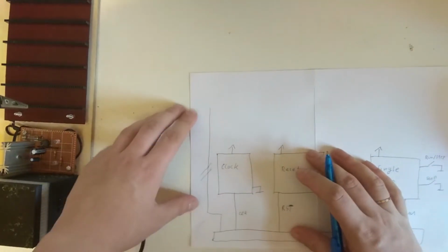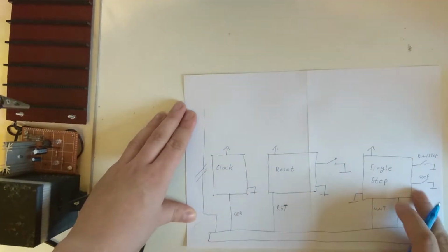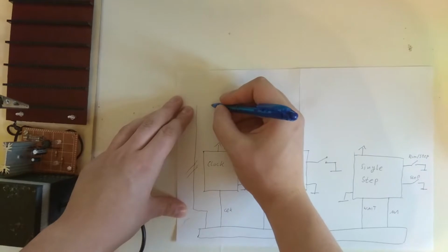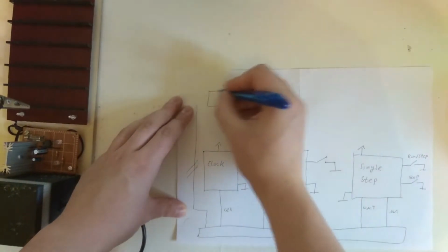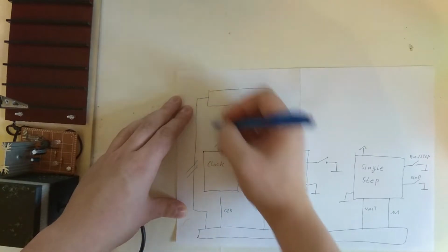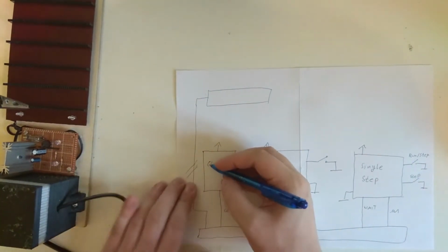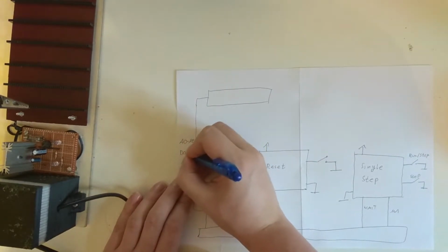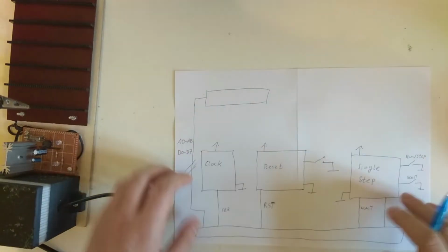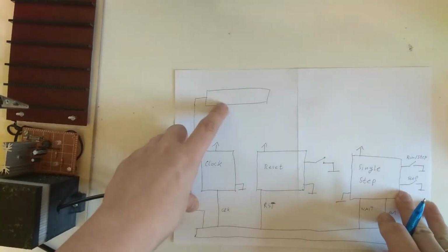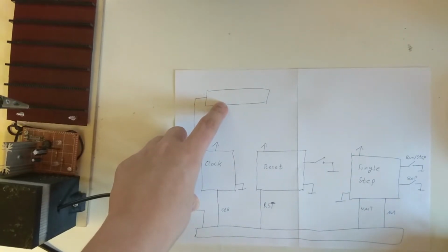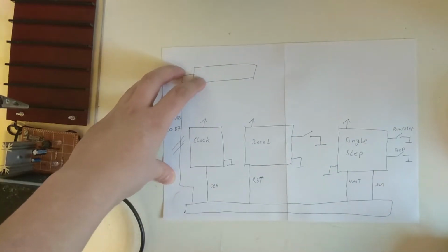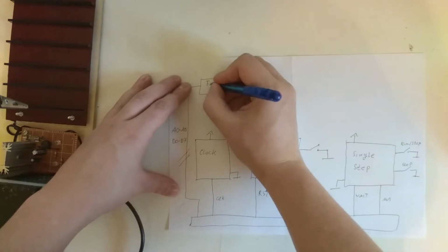Bus. I want this card, because this is not all that much circuitry for a card, I want this to have basically another connector on here that brings out the address, so A0 to A15, and the data lines D0 to D7. Brings this out to a connector so I can connect it up to a front panel later on, so I can have some blinking lights. That would be great. So this is just front panel.